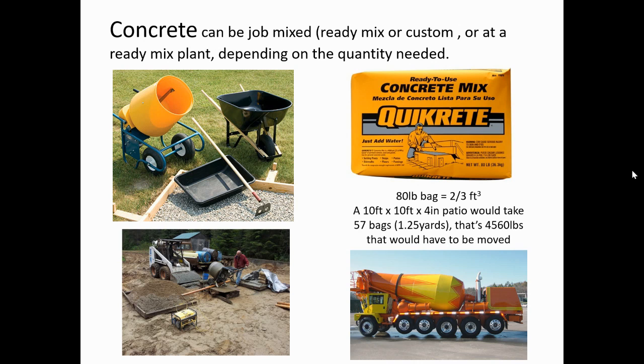What they've done is they've already combined the ingredients for us. In that bag is some sand, some aggregate, some rock, and some cement. What we do is we just pour it in our bucket, add the water, mix it up, and we can place our concrete then.